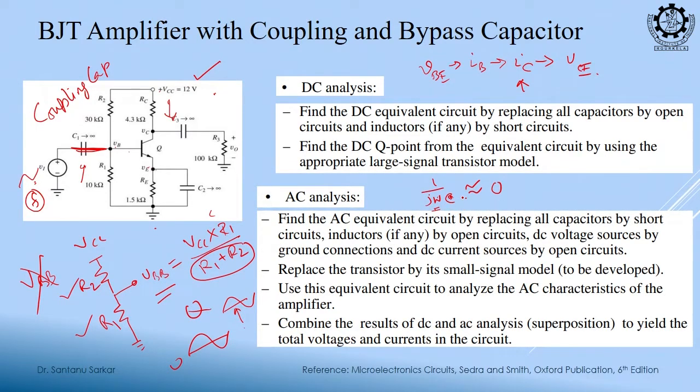Okay. So, this C value you should choose so that at the frequency of interest this should be short. At DC it should be open, but at the frequency of interest it should behave like a short. So, by default it is very large, microfarad or something. In microfarad means quite a big capacitor. Okay. So, this is my